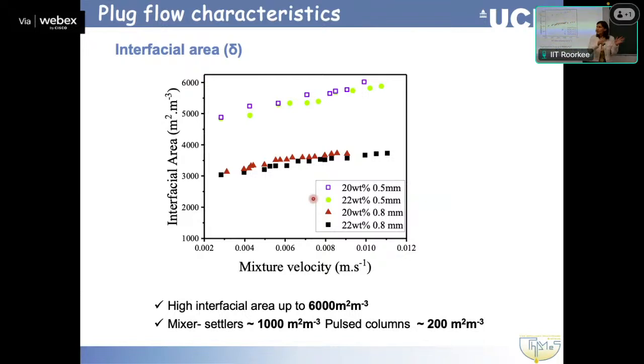And as we will discuss in 2 days' time, this increase in interfacial area is actually what sometimes makes the difference in the improved mass transfer coefficients. Other improvements we might get because the actual mass transfer happens faster are not as good or as large as this change in interfacial area.